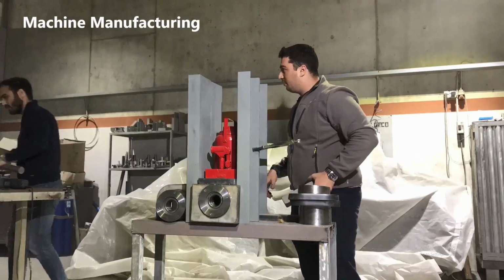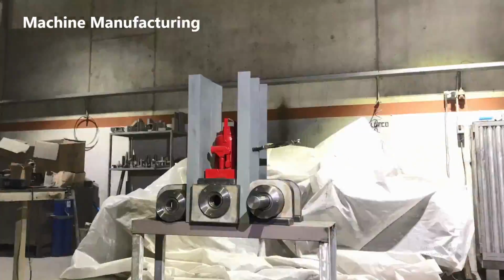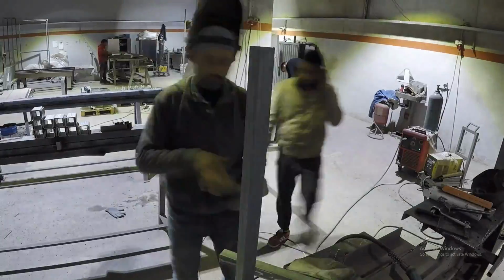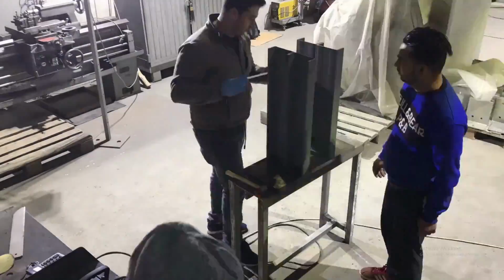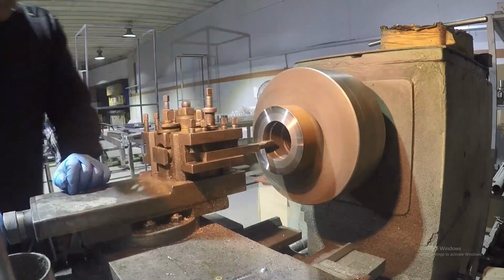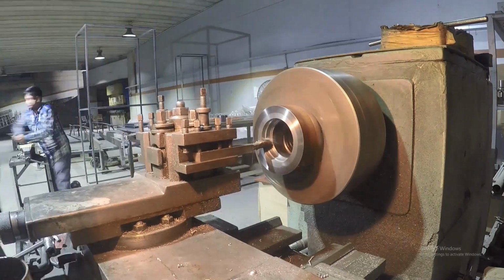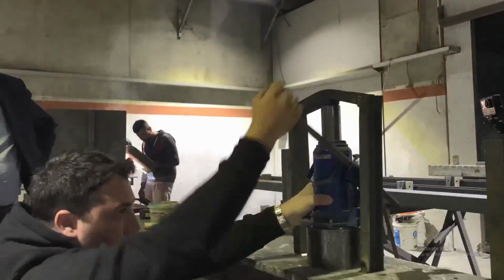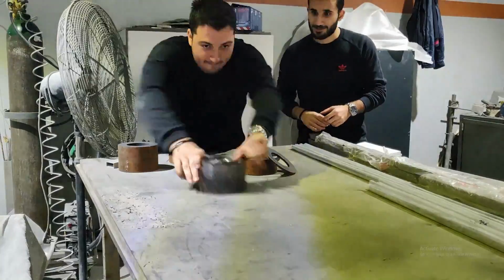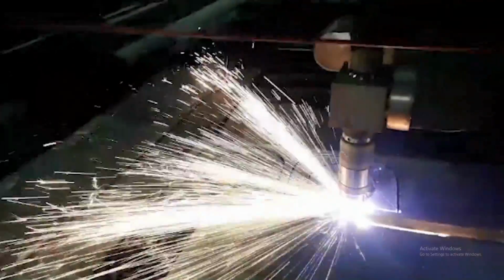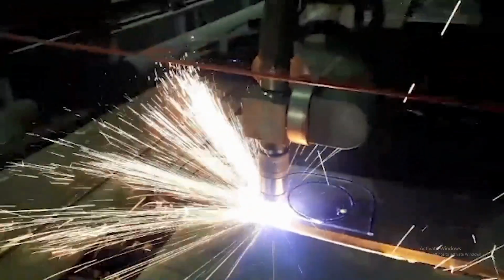After generating drawings and cutting lists from SolidWorks, we purchased the material and then started manufacturing the machine. A bandsaw is used to cut the parts like the UPN, bushings, plates, tubes, and other parts. Then lathing process for the shaft housings and caps. They were manufactured with specific tolerances for smooth contact movement. CO2 welding was used for higher strength and higher penetration, and a relatively faster process with a lower heat effect than conventional electrode welding. Many more tools were needed for drilling, threading, surface finishing, and cutting.